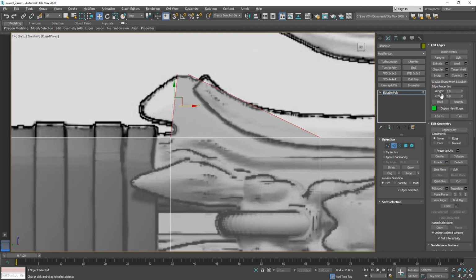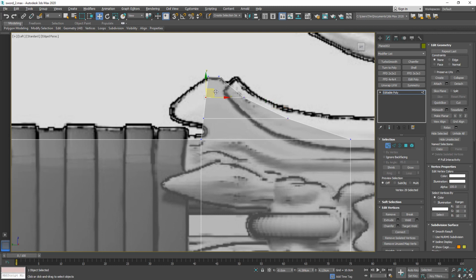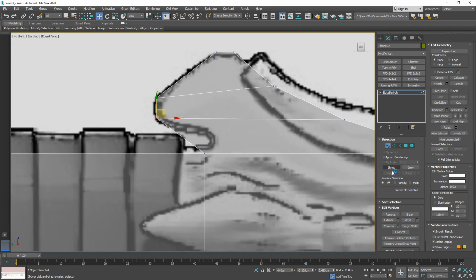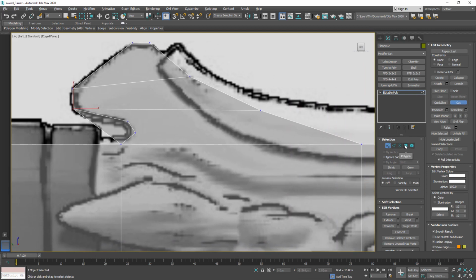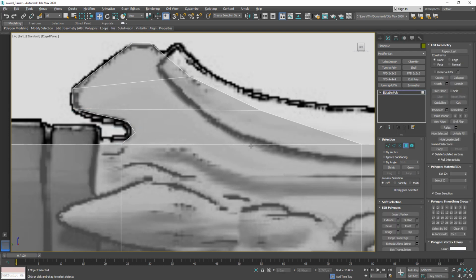And now let's go over again, do the same thing where we make an edge connection, but this time we're gonna have 2 edges in here to get a bit of a curvature there. So now on that side, I'm gonna drag that down here and this one to here. Let's go here to where it says cut. We're gonna bring up our cut tool, and that allows us to connect these vertices right onto that plane. Let's go here to the polygon mode and delete that face that we don't need anymore.